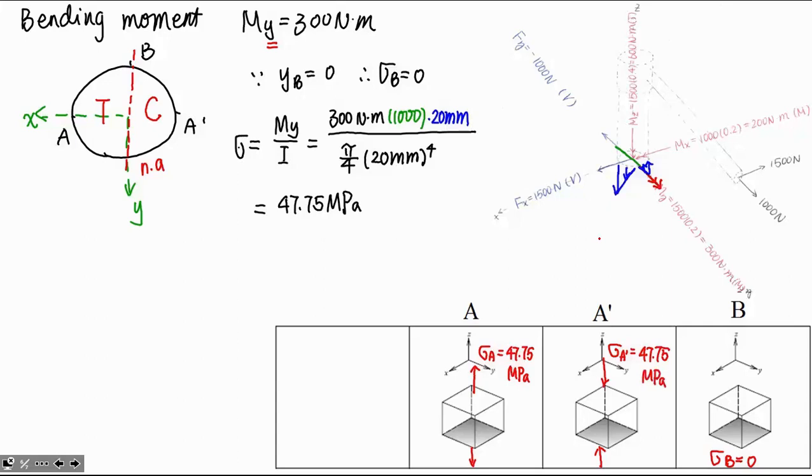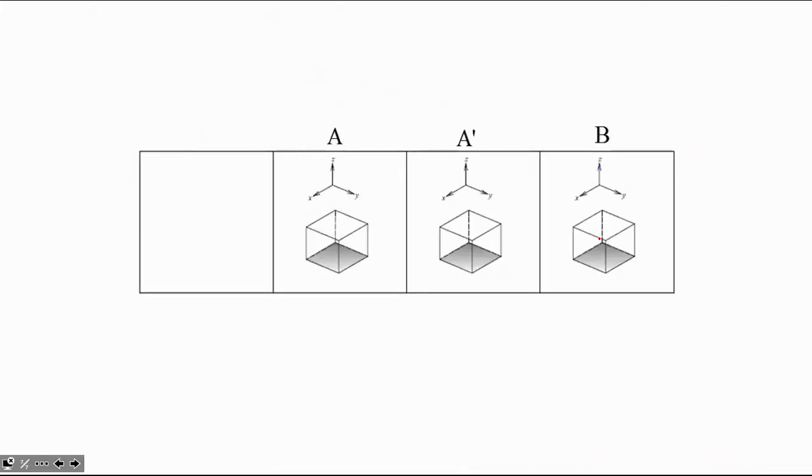Alright, we finished all the stresses for the different components, which means the last thing we are going to do is summarize them all. What you need to do right now is carefully add the shear stresses together and the normal stresses together. If they are in different directions, it's not just numerically adding the numbers up. Watch the direction.